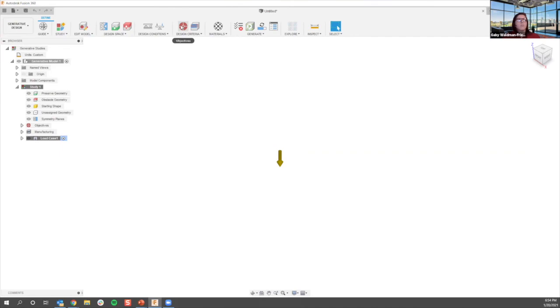And then the last thing is objectives. An objective is just specifying what the goal is. The default would be minimize mass, but you could also say, my goal is to maximize stiffness. This is my safety factor target or limit. And then you can also put in separate targets or limits for modal frequency, displacement, and buckling. And that's basically it.